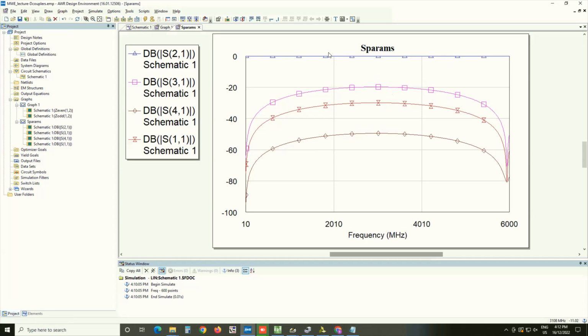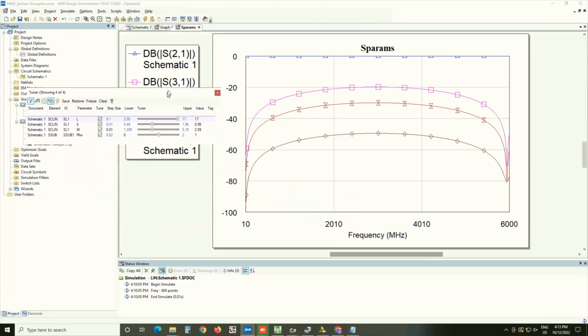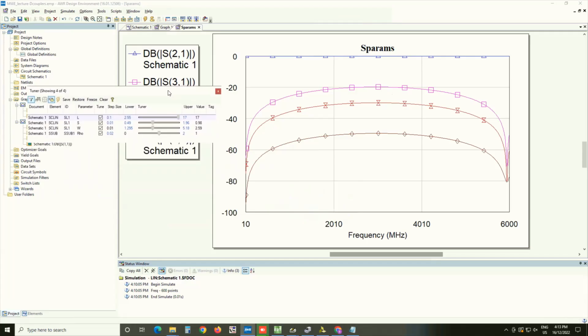Okay, so let's try to see if we can tweak the numbers. One advantage of this pre-solved model is that unlike the EM simulation, this is much faster. But it's still close to a physical model. It's not an ideal electrical model. It uses some formulas which have been pre-solved for a particular geometry, and then gives you a model here. So remember, the only 2 things we can control are the S and the W, so the width and the gap. The length has no meaning. If the length was wrong, the special frequency would be slightly off, right? So that's not so important for us right now.